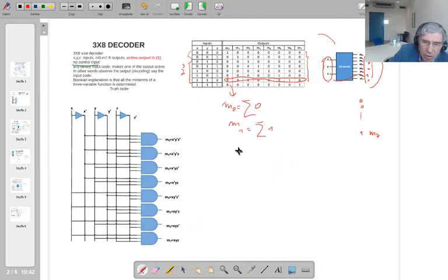So input is 1, that is M1. M2 is 2, it goes like that. M7 is 7, sorry. What it means is each of these functions has got one minterm, isn't it? That is a minterm. So we are writing the true minterms while we are defining our function. So what is written here is true minterms. Each function here has got one true minterm in it. The summation of the true minterms is the first canonical expansion, isn't it?